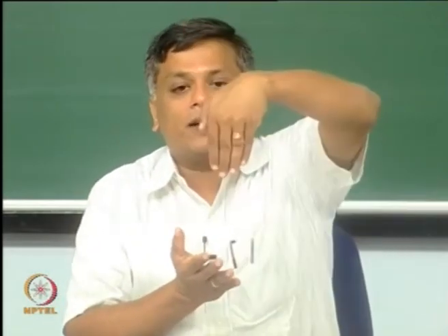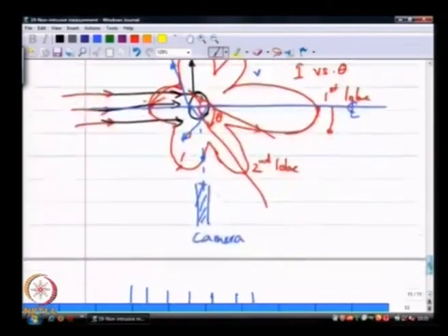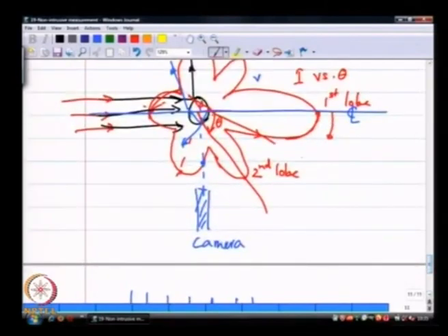Whereas, if the light coming in from the top and the region of interest is much larger than the camera, then I have light being scattered towards the observer from different angles in different parts of this rectangular image. If you go back to this Mie scatter pattern, the intensity of the light observed is different when observed from different angles.